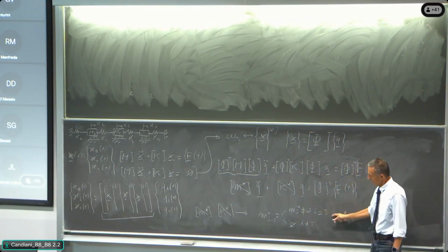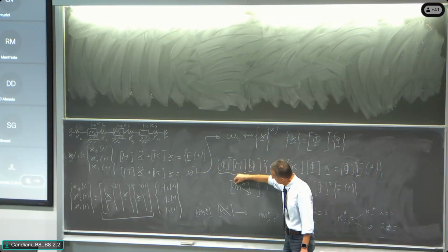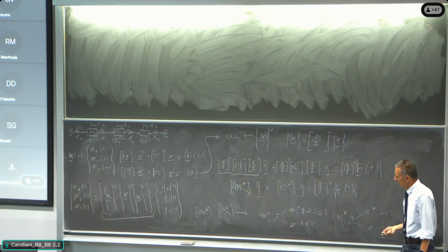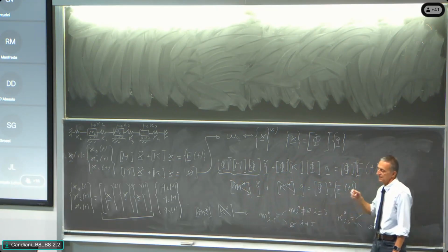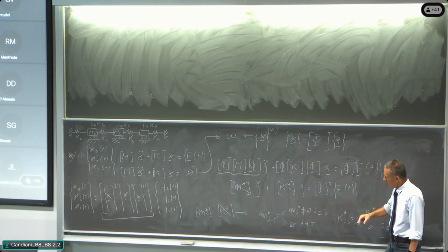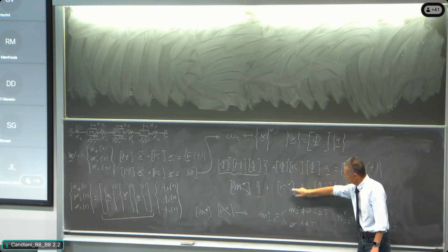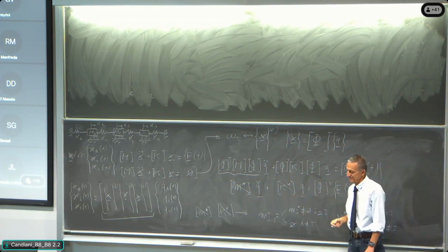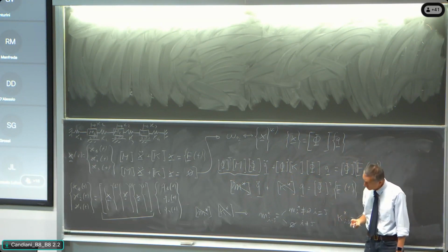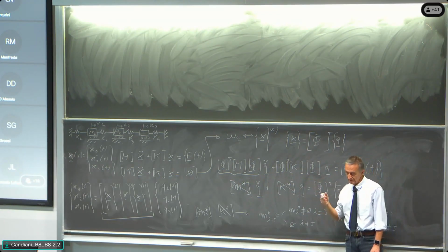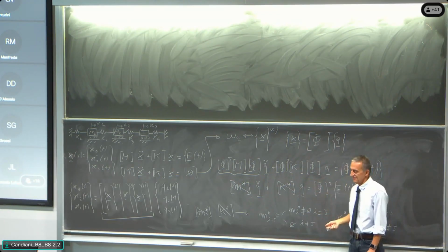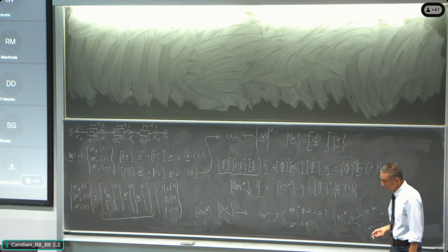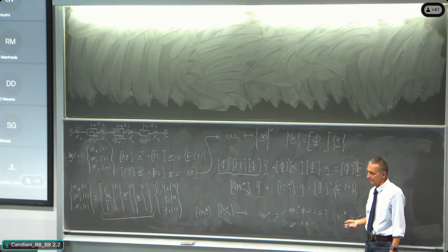So in the location 1,1, 2,2, 3,3, whatever, we have an object that we call Mi star, the modal mass of the ith mode. For the stiffness, we don't call it Kii; for example M1 star is the modal mass of the first mode, and K3 star is the equivalent stiffness, the modal stiffness of mode 3.